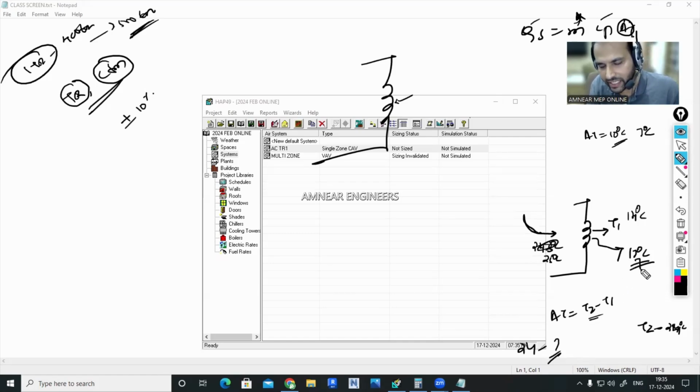Now this 17 degrees Celsius of air and the room hot air will mix together. Then we will be achieving that room set point of 24. Correct. Delta T is... if this amount of airflow rate is increasing, Delta T will decrease. Supply temperature will get affected.